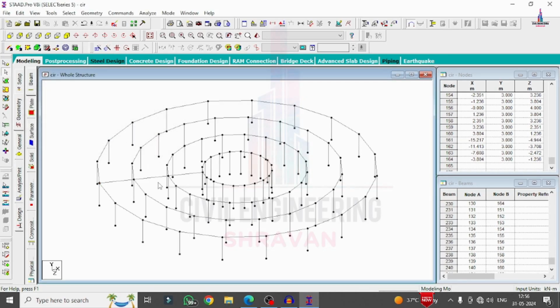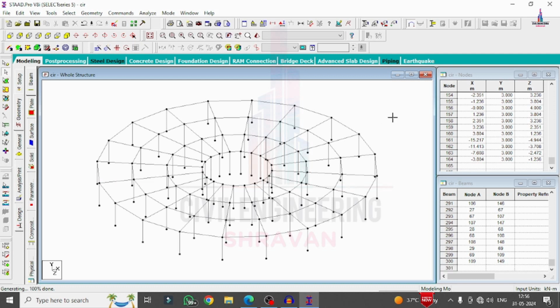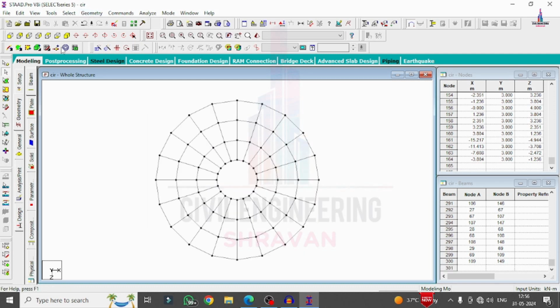So after this we have to copy these sections to the circular repeat option for this entire beam sections. Okay. So go to select the circular repeat in Y direction which is consisting of 20 numbers here. Click on OK. So it will create your models here like this. Now after this we will select the top view. We will delete all unnecessary beams and columns which is required to make the lift provision as well as the staircases for this building model.